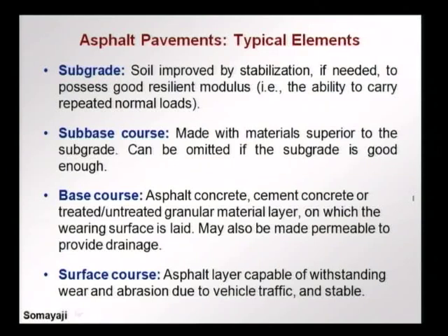On top of this subgrade, generally you will have a sub-base course, and this is made with material superior to the subgrade. If the subgrade is good enough, that is it has a high enough resilient modulus, then it is not necessary to have a sub-base course. The base course can be directly laid on the subgrade.